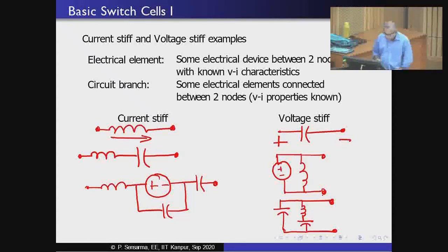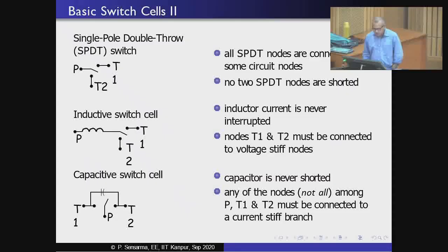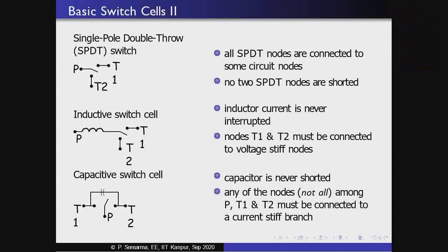Okay. So, having said all that, let us see how we can formulate some of the basic converter circuits. Before that, we need to do one more little exercise. As you can fairly well appreciate, if you put a simple switch in series with an inductor, the moment the switch turns off, you go into a discontinuity. Now, as we have so often previously emphasized, that is not something that we are going to allow in the circuit.